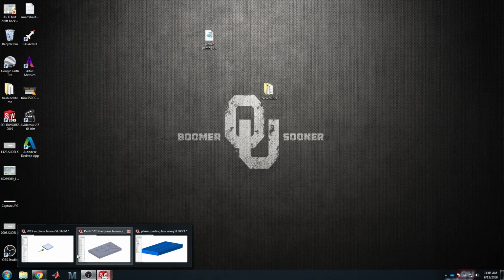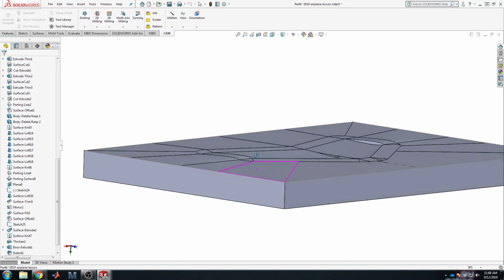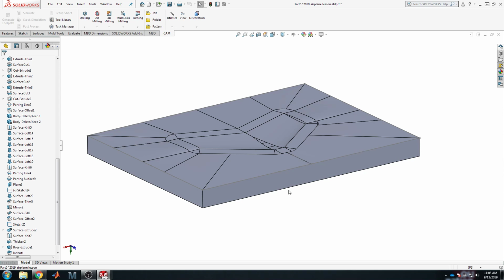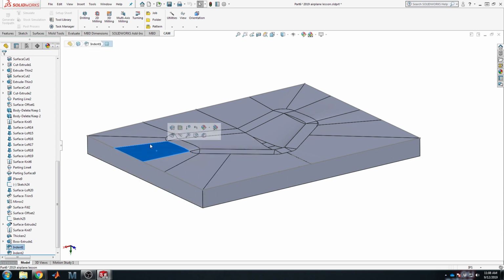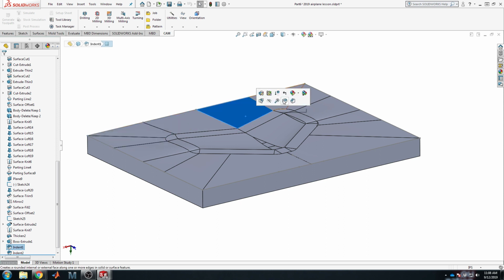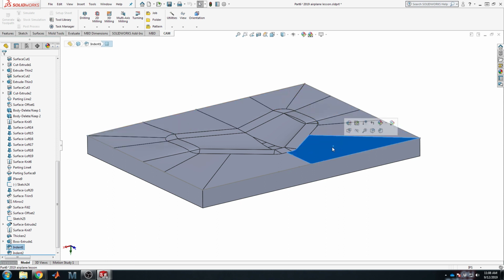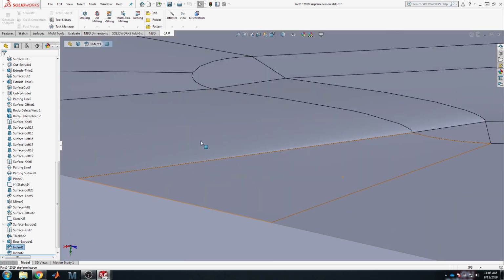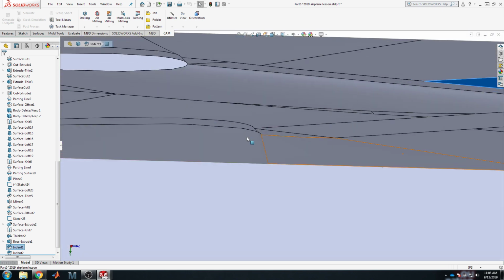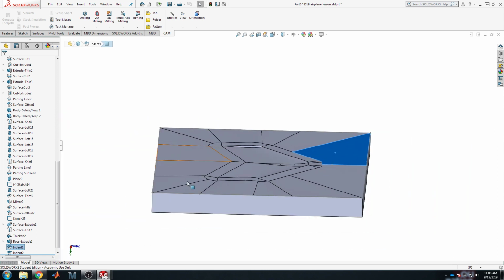And it's all about the same for doing a non-planar parting line mold, with the exception that now you have to do the entire surface with a ball nose bit. You don't have the luxury of having a flat parting line out here. You don't have that flat planar region. It's going to be curvy. So you don't get to accelerate and reduce cutting time by using a large flat 1-inch diameter cutting bit, you're stuck with using ball nose bits all the way around, and it just takes longer.